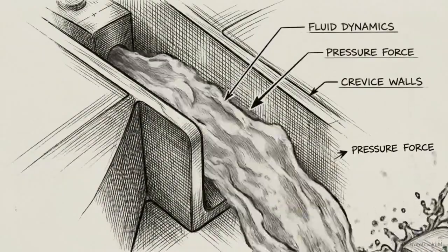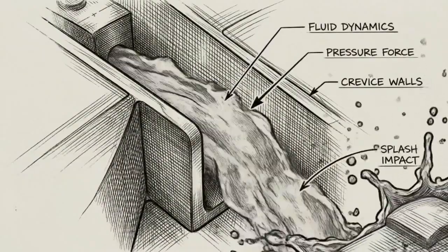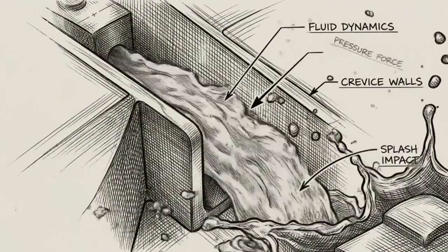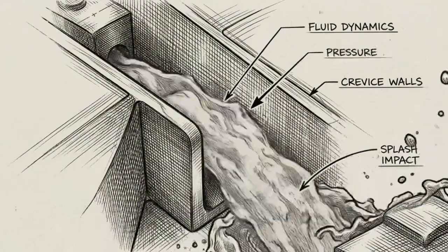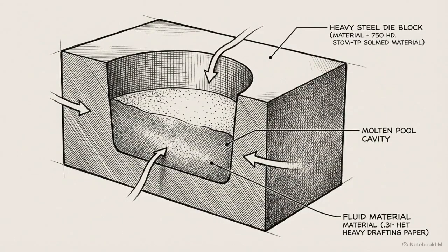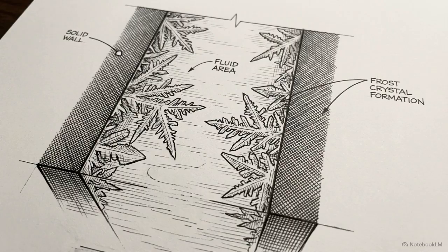High-pressure die casting, or HPDC, forces molten aluminum into a steel die at extreme velocities, applying pressures that reach up to 2,000 bar. Immediately following this violent injection, the molten metal meets its secondary constraint, a massive thermal drop. The cold steel die triggers a near-instantaneous cooling cycle, freezing the liquid aluminum in milliseconds.